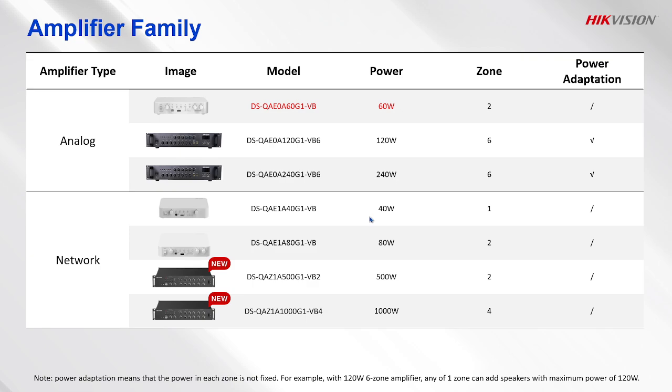But remember, you need to reserve 20% when you're calculating power. So let's say I give you a 100 watts amplifier. The maximum you can load on it is actually 80 watts. So consider that in your design for the audio solution.